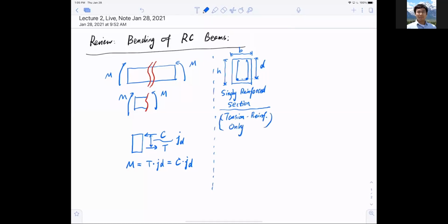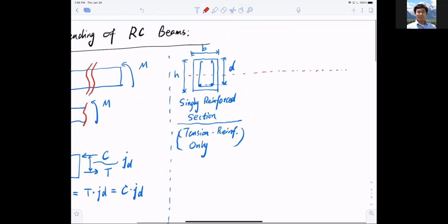All right, that's the equivalent term of singular reinforced, because we'll talk about a double reinforced later, which includes a compressive reinforcement. Okay, so extending the neutral axis line, I want you to remember this because you need to draw this strain distribution, stress distribution, internal force distribution in your homeworks and in the exam because you receive partial credits, okay?